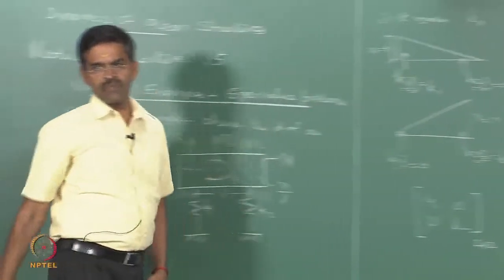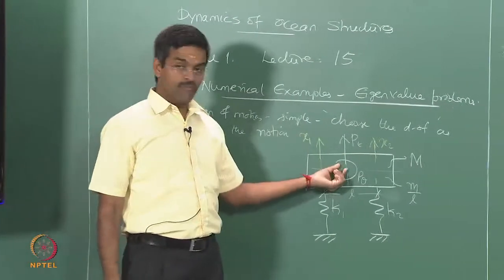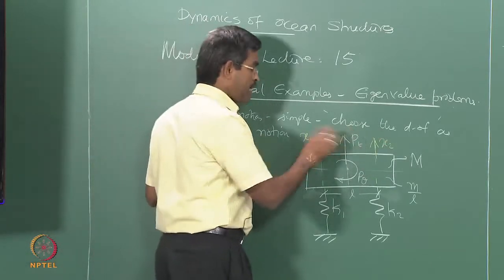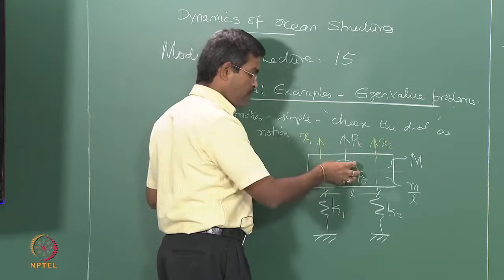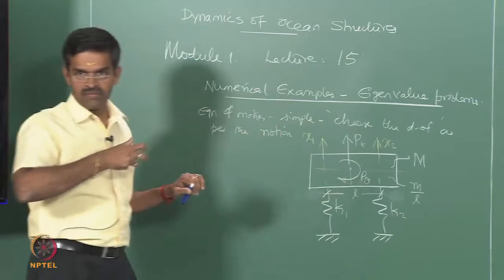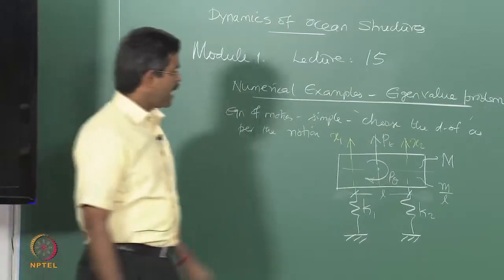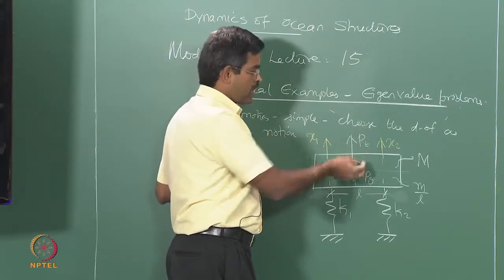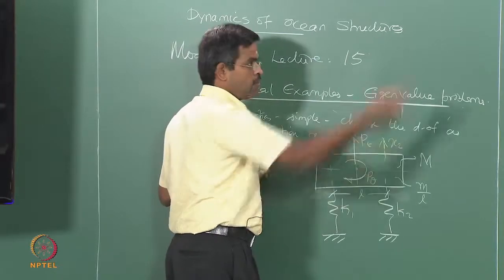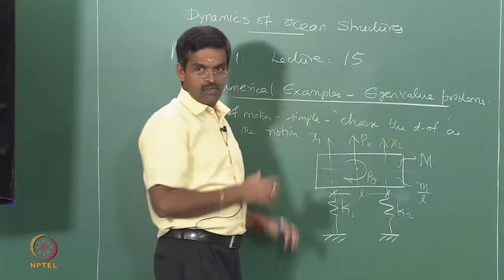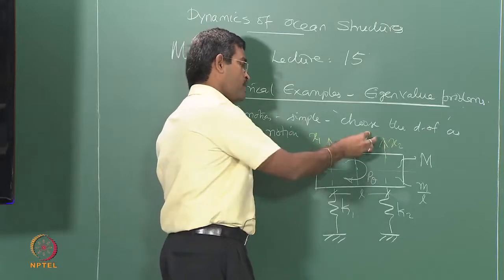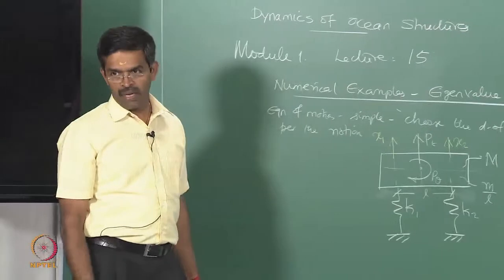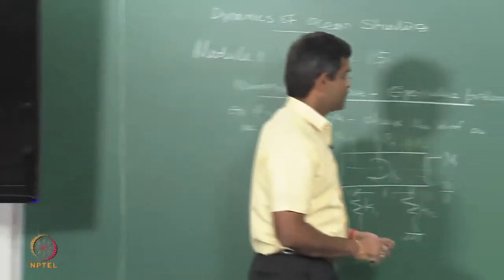Now, why am I deriving a force vector? Because force is applied at a point different from that of the degrees of freedom. I want to know the contribution of Pt at x1 and x2, and the contribution of P theta at x1 and x2 locations; they are different. If x1 and x2 had been located exactly here and here, obviously x1 and x theta, then Pt and P theta would be a simple vector. But in that case it is not so, because the contribution of Pt at x1 location, x2 location has got to be derived, they are not applied. Okay. Let us derive this.